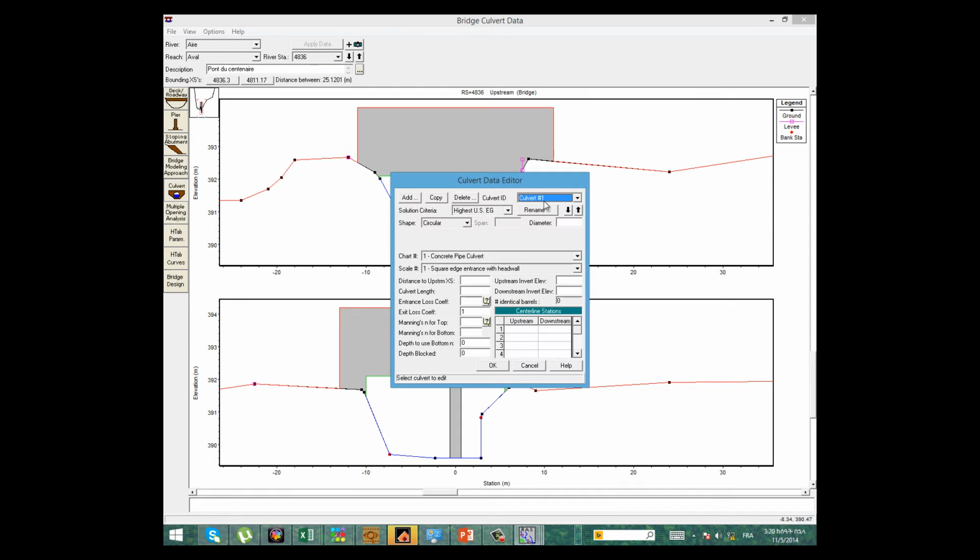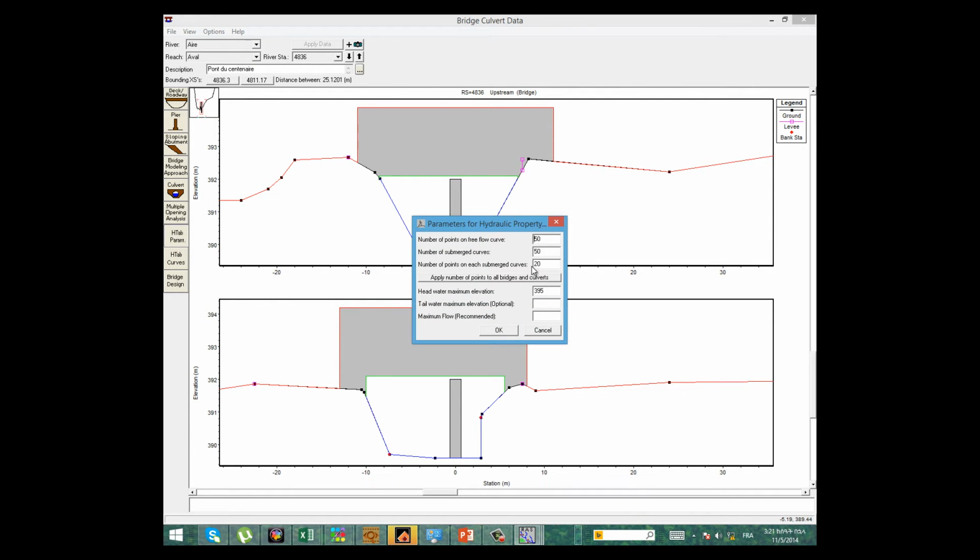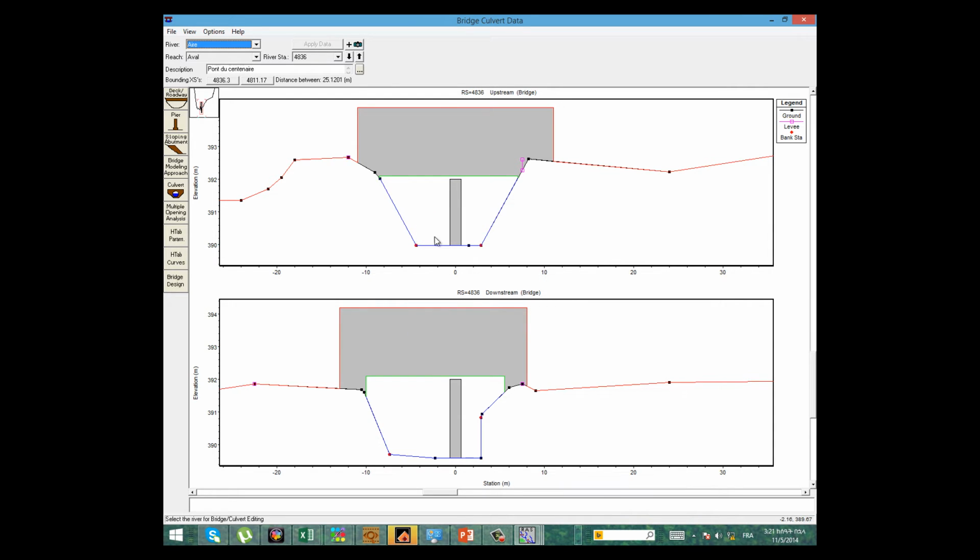If we have a culvert, we also put culvert. We just give a station and hole diameters and so on, and edge parameters. This is just a storage elevation curve. So if we need to have a storage elevation curve at the bridge, we can put that thing. So we have almost 5 bridges along the river, along the segment. You see, we are considering the river Aire.